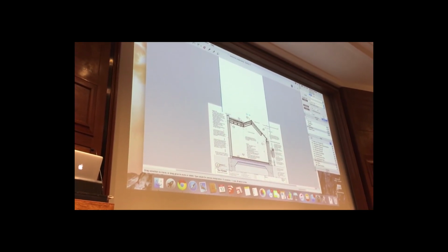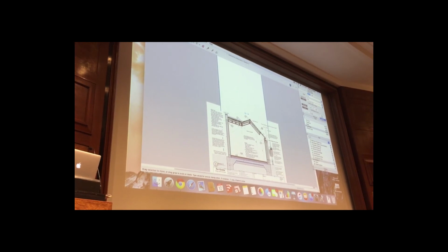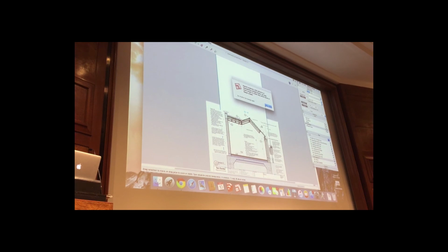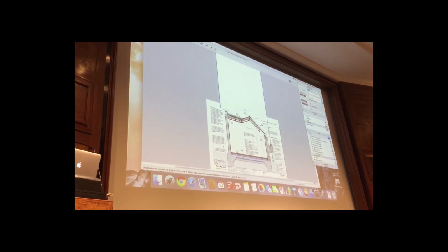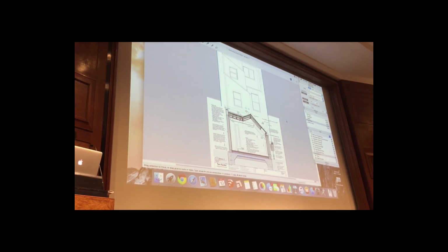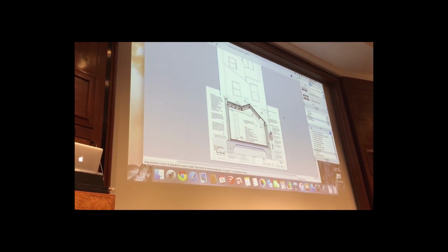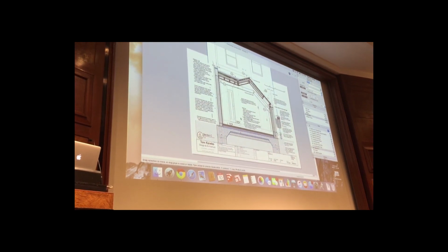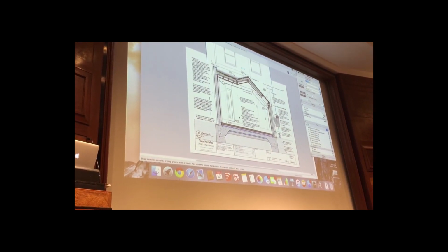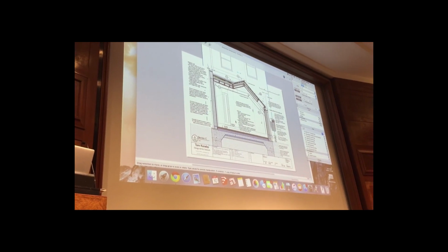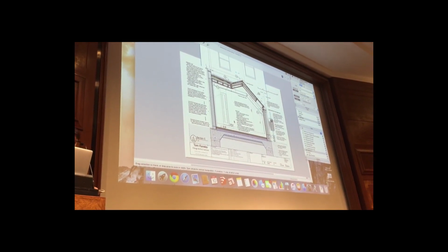All you want are just line drawings behind. You just use that fog tool, and then you put your scene into hybrid rendering mode, and then you get all the lines behind. And the great thing about this, obviously, is that you get the solidity of the section, and that's what you're looking at. Everything else behind becomes irrelevant, I suppose. And that's how you make really good drawings.